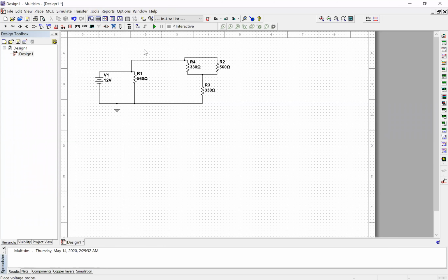I'm going to grab a voltage probe, and I'm going to click to place it where I want the voltage to measure. Right now it doesn't say anything for these readings because I haven't run the simulation yet, but when I do run the simulation, I will get some readings by default here with respect to ground. I'm going to put a current probe in the same spot, actually.